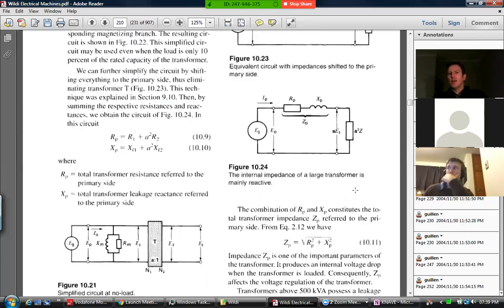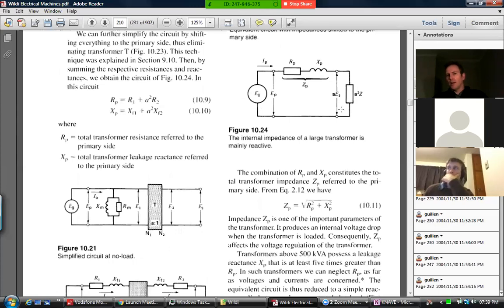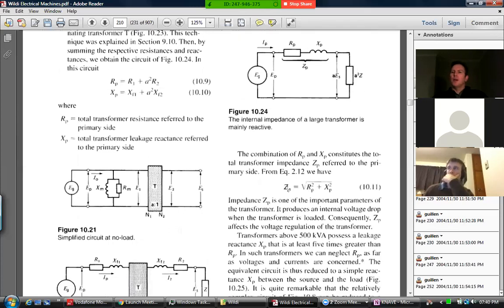And then we can actually analyze how much current flows here, because you can analyze the circuit as these things in series. And at the end, we can convert back again to the voltages that the load will see versus the voltages that you'll see across these internal. So it's a little bit like a battery with an internal resistance. We'll have an internal impedance here and then a load. And the internal impedance will steal some volts so that the load won't see everything. It'll see a portion. Okay, but that'll be for next time.